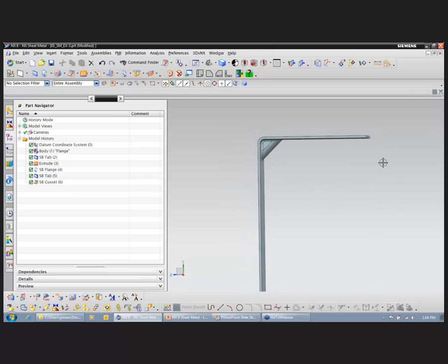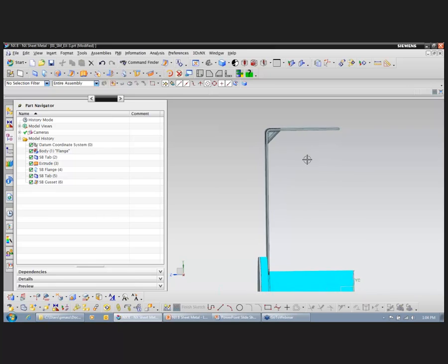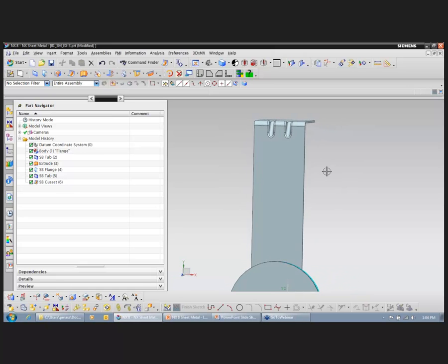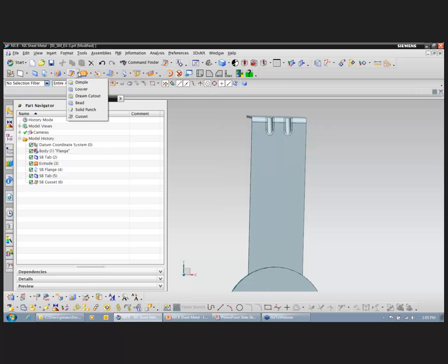So now we can see the top end of our bracket, this cantilever beam that's sticking out here. It won't be so flimsy; maybe we could put a little bit of weight up there now. But we still have the second part of the base tab of this flange that maybe could flap in the wind or might be wiggling back and forth due to vibration. So in order to add some rigidity and strength to that, I'm going to apply some beads to this back face. Under the same drop-down menu, I can choose the bead command.